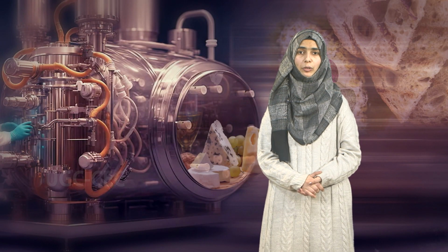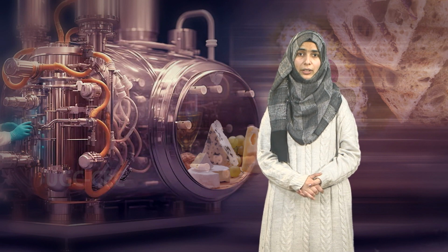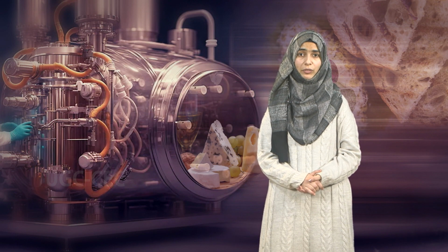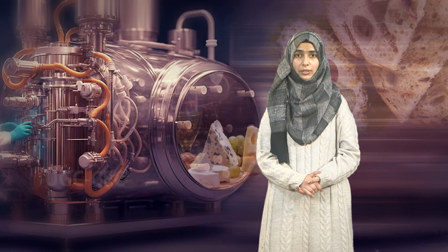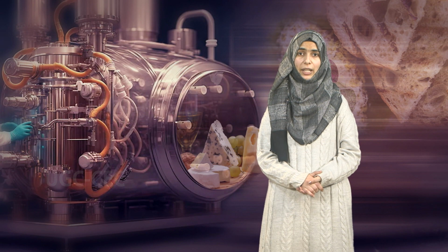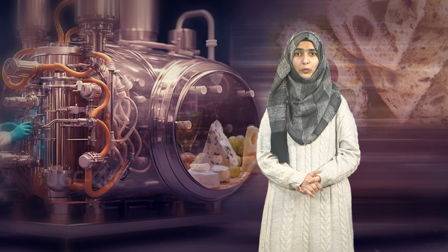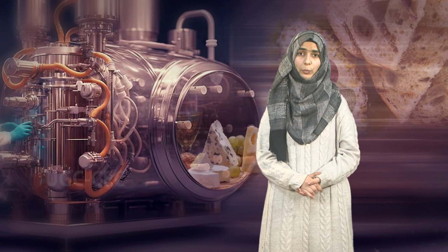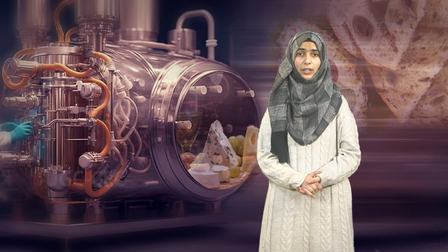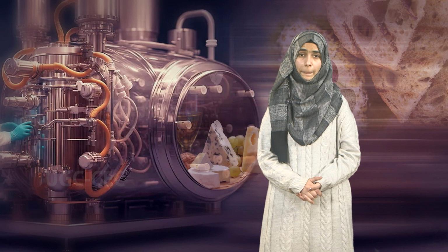In many high-value processes, the bioreactors will be operated in a batch manner under aseptic monoculture. The initial culture expansion of microorganisms will commence in the smallest bioreactor, and when growth is optimized, it will then be transferred to a large bioreactor, and so forth until the final operation bioreactor. Throughout such operation, it is imperative to maintain aseptic conditions to ensure the success of the process.